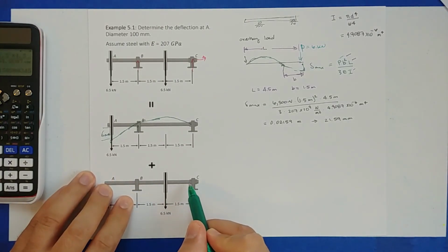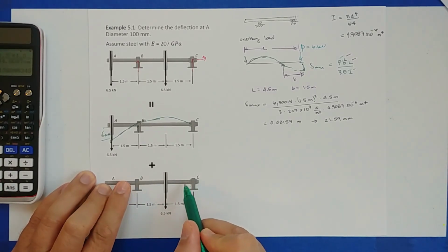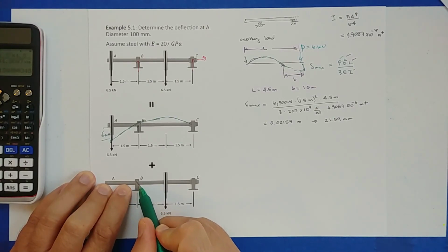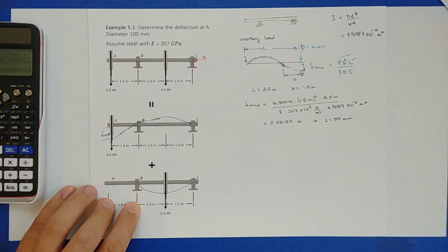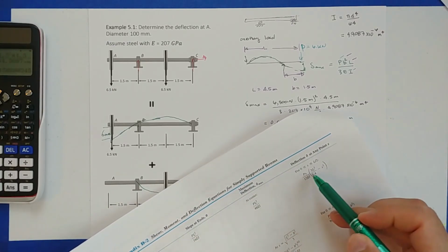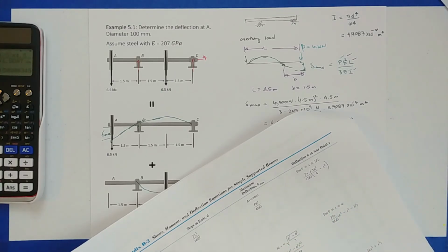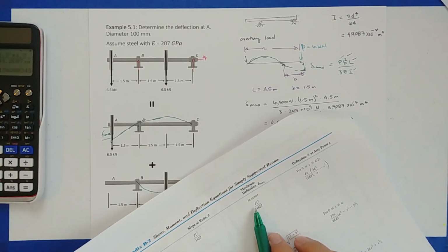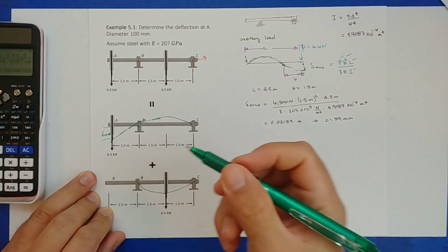How is this beam going to deflect? Well, if I have a load going down and it is right smack in the middle, this is going to make that shaft or this beam kind of smile like this, right? If we look at the equation booklet, we have equations for anywhere here in the middle. We have the maximum deflection, which happens at the center. But in this case, we want what's happening over here at this end.